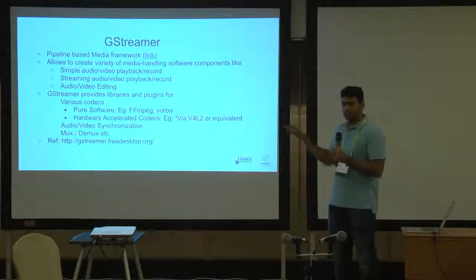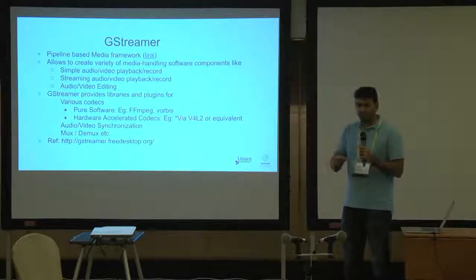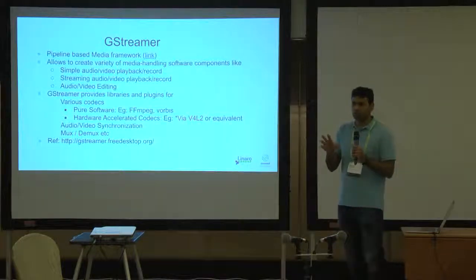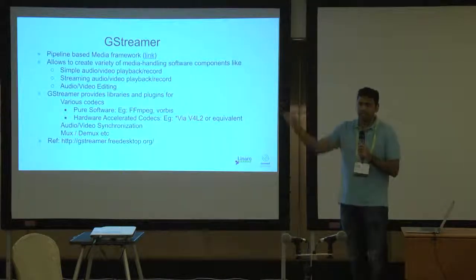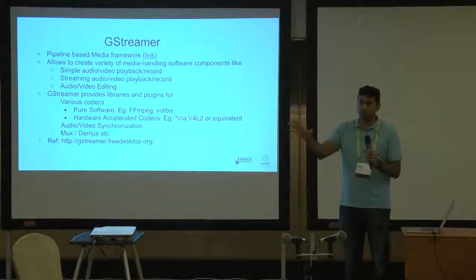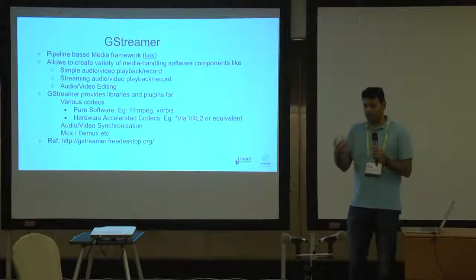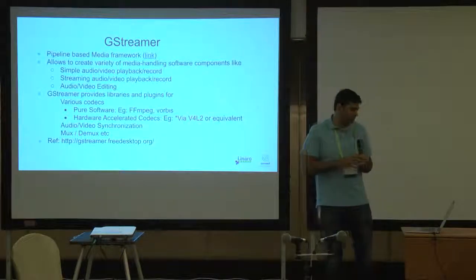And the great thing is, as of the GStreamer 1.0 release, if your SoC implements a V4L2 driver, you almost don't have to touch anything in the user space. I didn't have to touch anything in the user space. GStreamer just worked. Why? Because GStreamer standardized the interfaces for talking to the V4L2 node. So the open calls, ioctl calls, querying about what capabilities the decoder has, it's all standardized. And an even better thing is that the V4L2 plugin is already part of the GStreamer project now. That's the best thing about it.